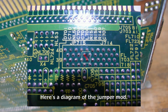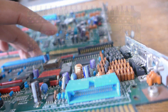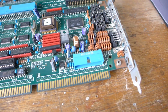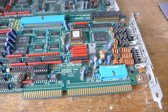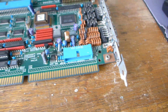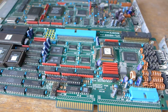It seems pretty easy to do. So the reason why you need to do this is that if you don't put a terminator on the CD-ROM drive connector, then if you try to use the SPU, your programs will lock up, or I think it will even lock up without even using the SPU. So I recommend having a terminator set there.